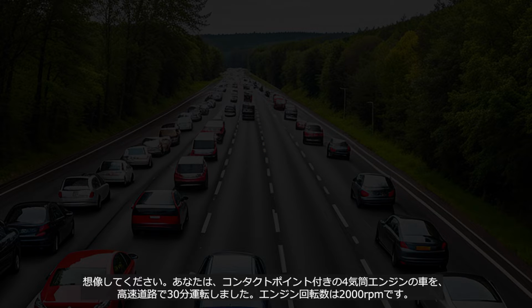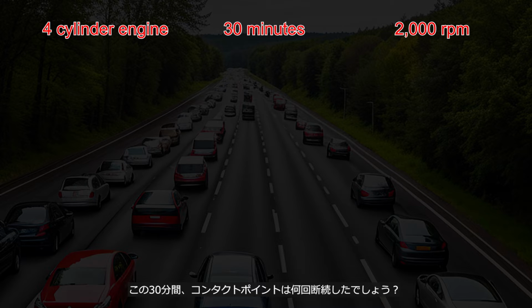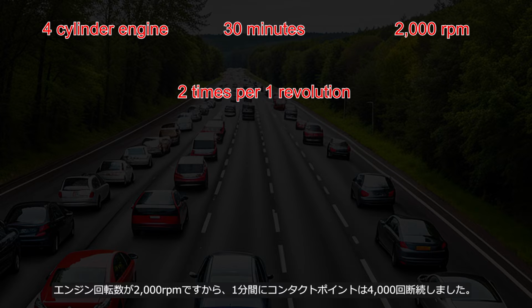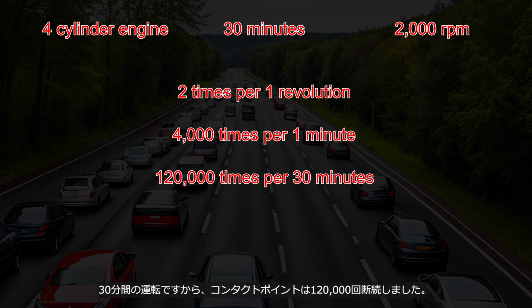Imagine that you drove a 4-cylinder engine car with a contact point for 30 minutes on a highway at 2,000 revolutions per minute. How many times did the contact point repeatedly connect and disconnect during this 30-minute period? Let's do the calculation. The contact point connects and disconnects twice per 1 revolution of the engine. Since the engine speed was 2,000 revolutions per minute, the contact point repeatedly connected and disconnected 4,000 times per minute. Since you drove for 30 minutes, the contact point repeatedly connected and disconnected 120,000 times.